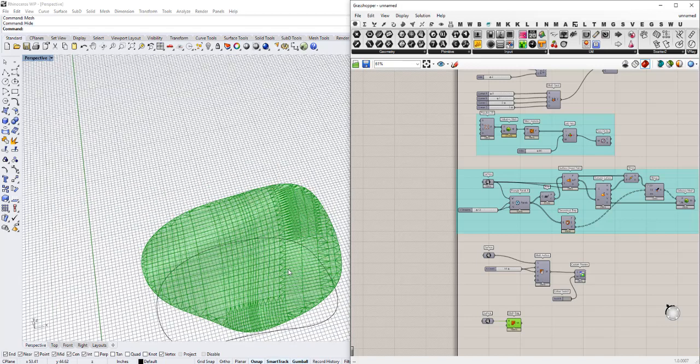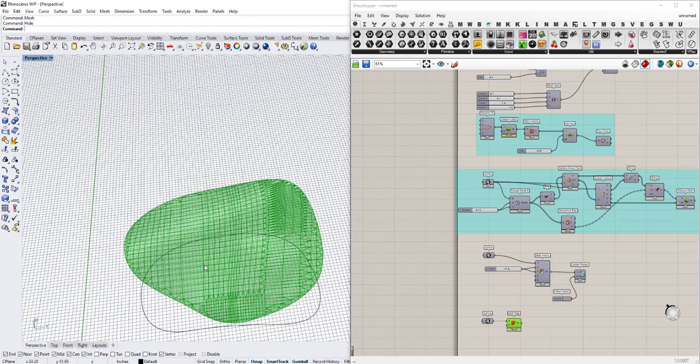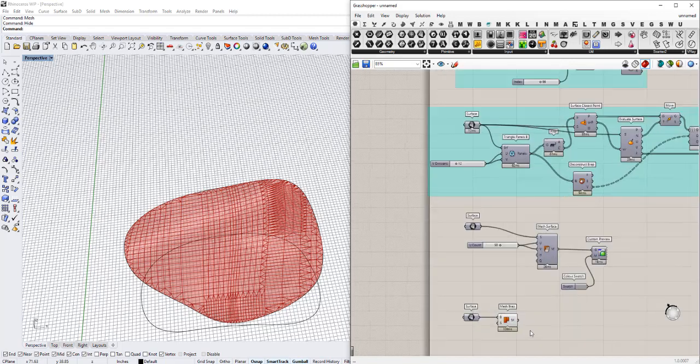You have a mix of triangular and rectilinear mesh faces because it's clipped on the outside. It has all of these weird sort of edge conditions where it's trying to make those fit better. So that's really not the topology we want, especially if we wanted to use that for some sort of simulation or control geometry for some other sort of structure.